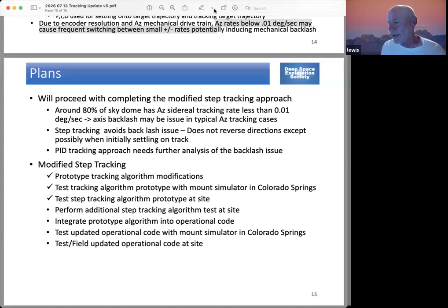So if the wind adds extra load, resulting in needing extra torque to hold it, the motor controller should handle that pretty well. Basically the system one is a position controller, and it uses rate to control the position, and then the motor controller controls the rate. That's kind of the way the current system works. But the motor controller has no special mechanisms in it for those types of things.